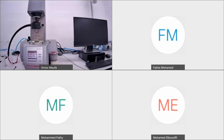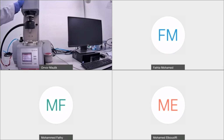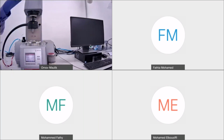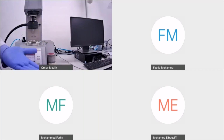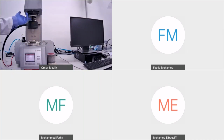Those who have not joined yesterday, I will explain some details about this rheometer. We have a motor head which gives the deformation and measures the torque, that is the stress. When you divide the stress by the deformation, that is the strain, you get the shear modulus. Then we have an air bearing coupling.